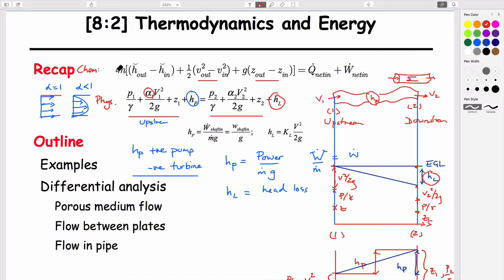And this is the pressure head term. The mass flow rate is always positive. But this term, H, is enthalpy. And it's not equal to the same head that we're talking about here; it's equal to internal energy per unit mass plus, I think, pressure divided by density. So the pressure head term still exists in here, but it's supplemented by chemical energy or enthalpy in the system, which can be transformed. So it's just written in a slightly different way.